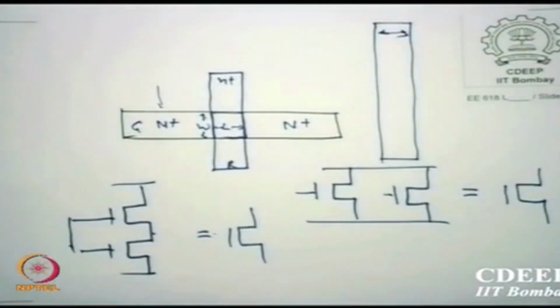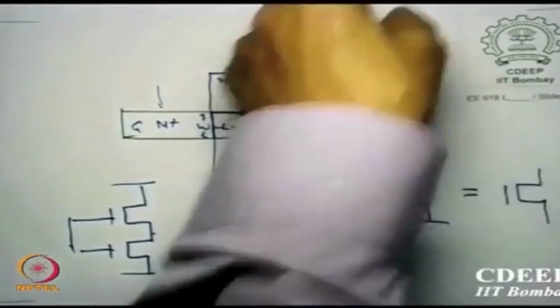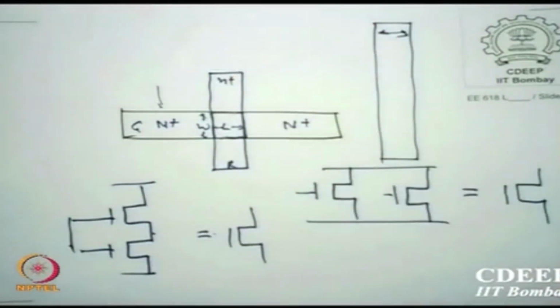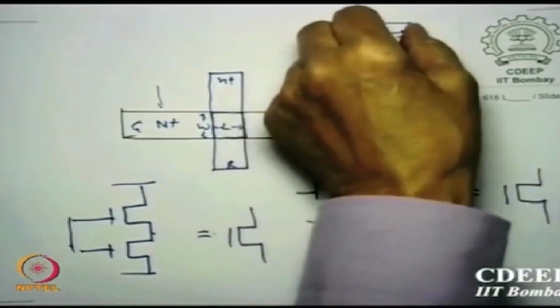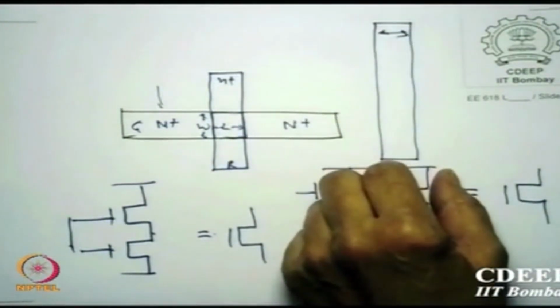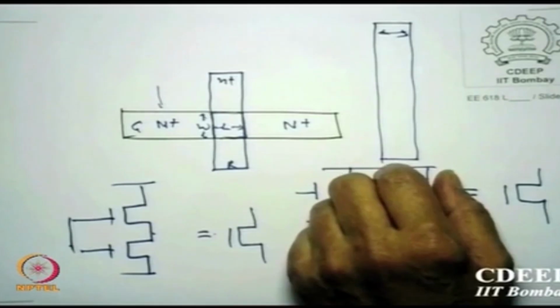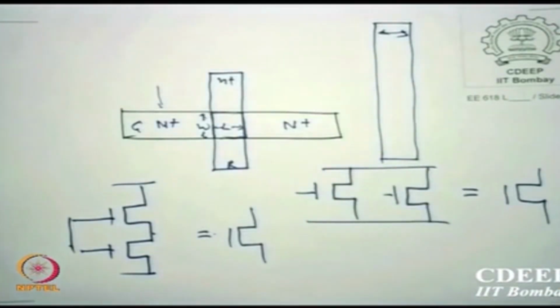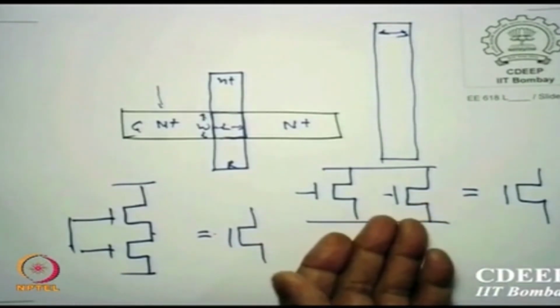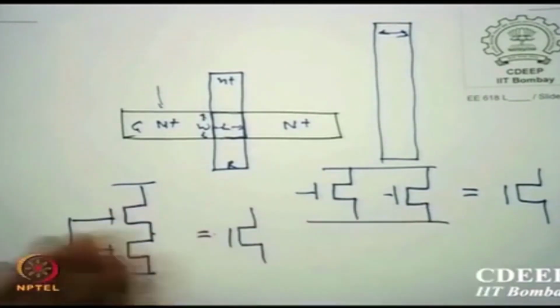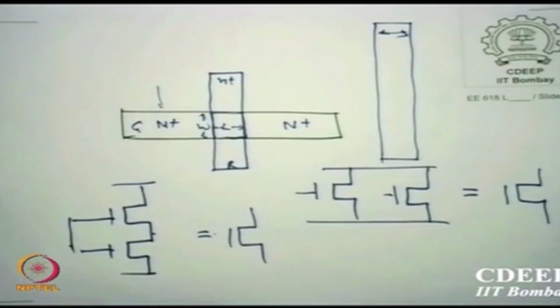Whenever I do etching, I cannot guarantee the etching here to here is the same, because I am going through a huge length. So the length here may not be the same as the length here. This is called the aspect ratio issue. So don't run too long lengths. Break into as many devices as you want, using either method, whether you want W higher or length higher, to equivalently put a large number of devices.